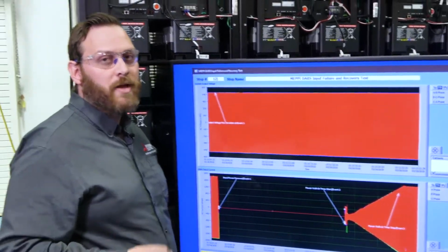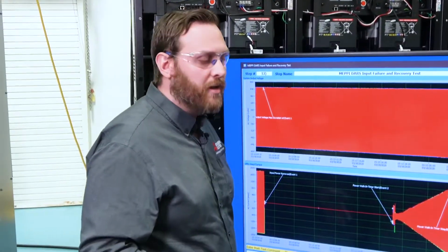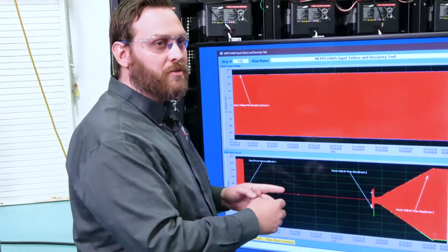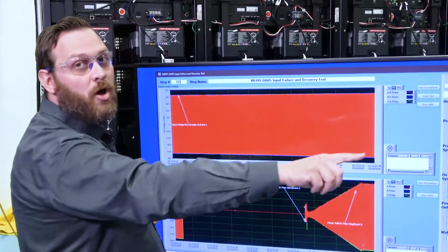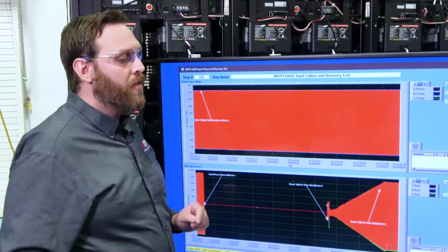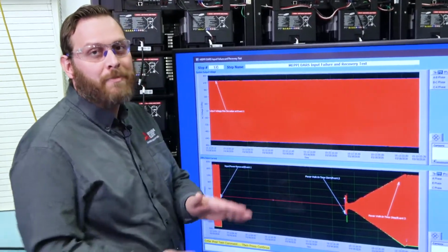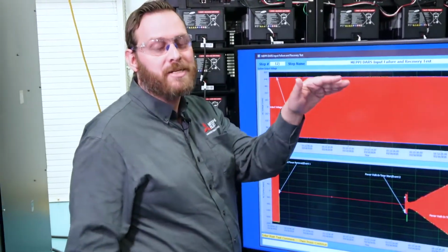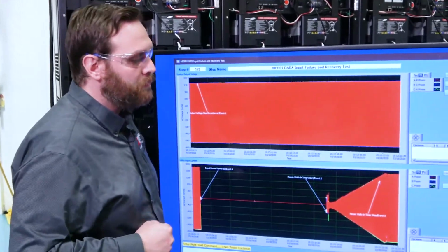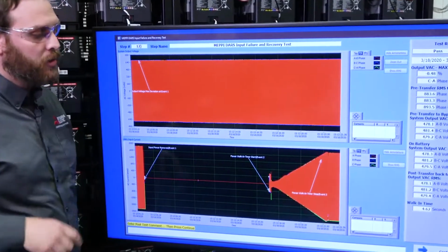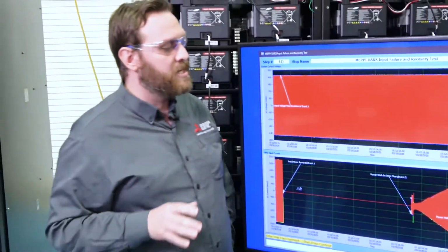Another interesting point is if you have natural gas generators instead of diesel generators, you can actually extend the walk-in to a much longer period of time, and that generator has lots of time to slowly ramp up operation before the UPS puts all the load onto it. So let's take a look a little bit closer at these transition points.